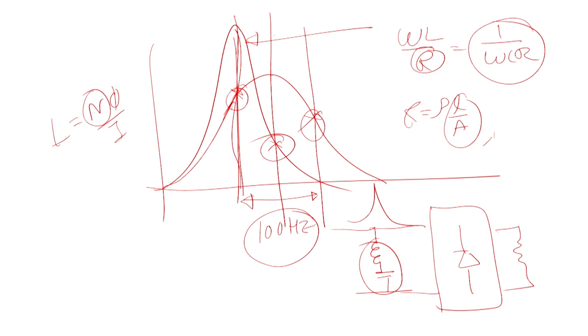So, ultimately to increase the quality factor, you essentially have to play with the cross sectional area. To have a high quality factor, you require to choose from a table called AWG, or conductor gauge, generally AWG. So, you require to choose the higher AWG to have generally close to 60 quality factor, and if you want this kind of thing, you require to reduce the cross sectional area.